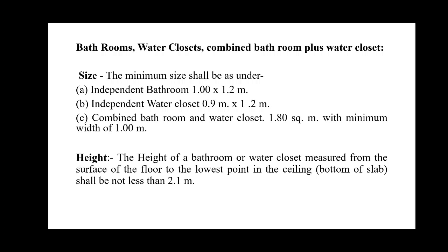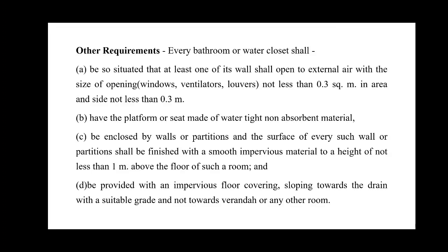Height. The height of the bathroom or water closet, measured from the surface of the floor to the lowest point in the ceiling, that is the bottom of the slab, shall not be less than 2.1 meters. The other requirements.